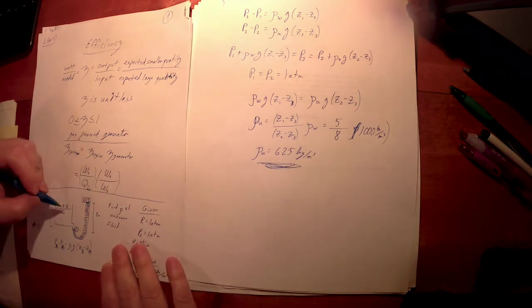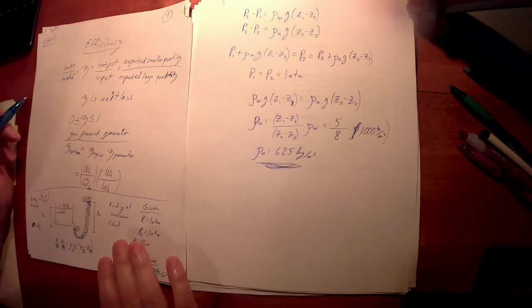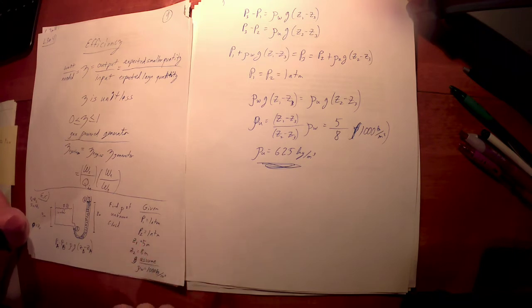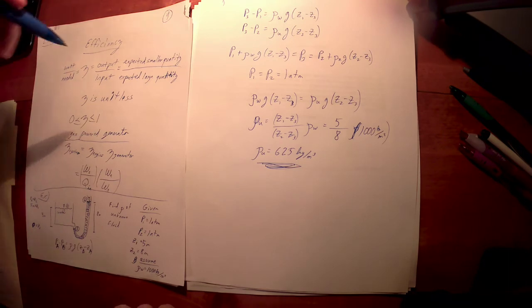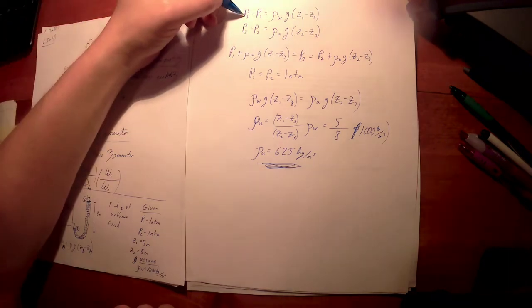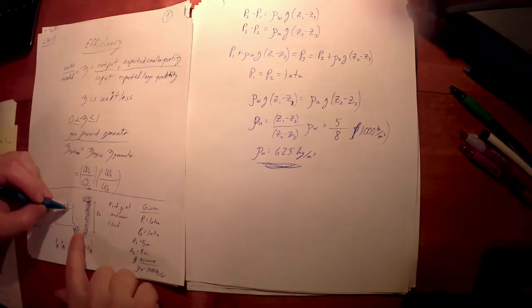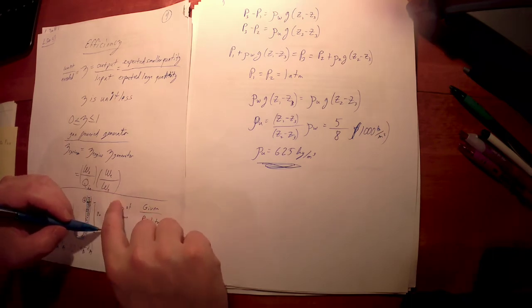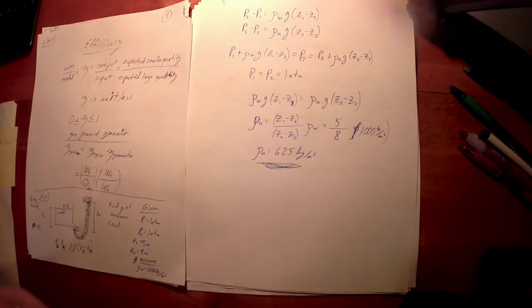There's a method that says, if you want this pressure, you start at this point, you add this, and you subtract that. That works if you want to memorize all that and figure it out, and that's okay. I don't mind that if that works for you. I don't do manometer problems often enough to get that right every single time. I can get this right every single time. I can set up one equation for this column of fluid. If there's another column of fluid, I can set up an equation for that one. And then I can splice those together using algebra. I can do that correct every single time.